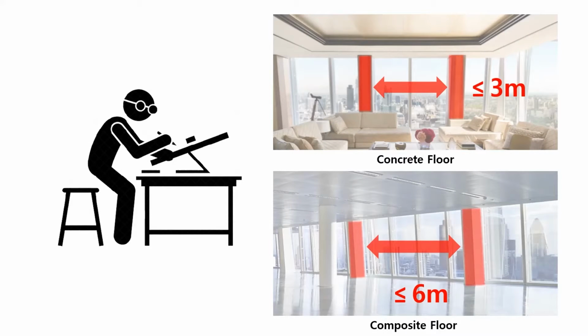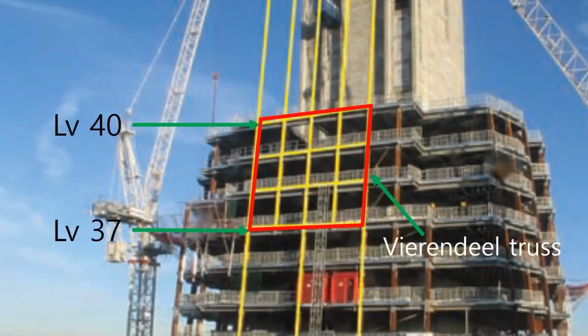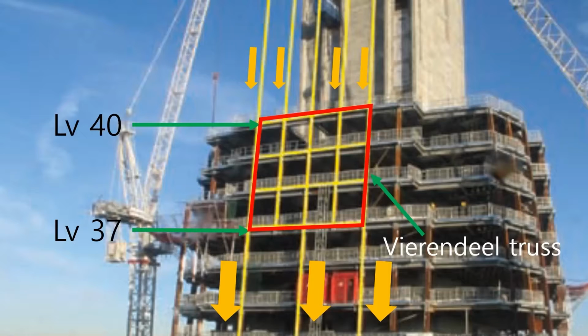Engineers found a solution to connect these two different columns. As a solution, in levels 37 to 40, the top of the steel levels, a blended truss changes the span of perimeter columns from 6 meters to 3 meters.